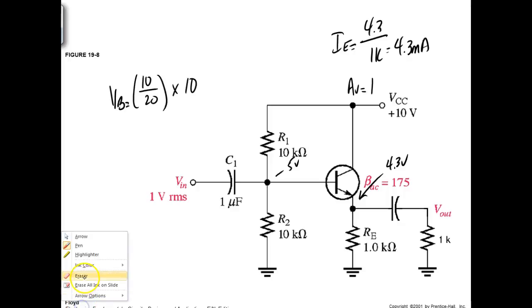our input resistance, this one in parallel. So here goes my AC. Comes flying in, goes through the capacitor. If we choose the capacitor the right size, we're going to ignore it, right? Comes over. Here's that point. What does it do? Goes up. Goes through the power supply. AC sees the power supply as a short circuit.